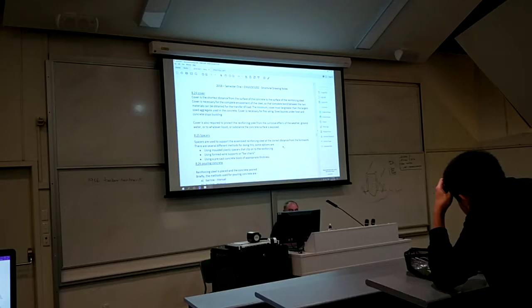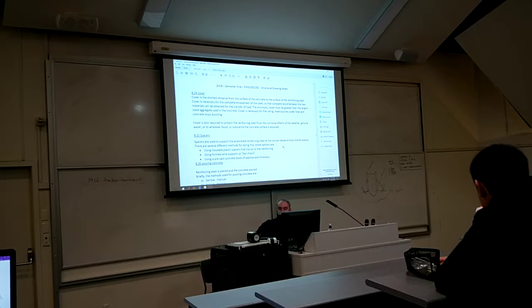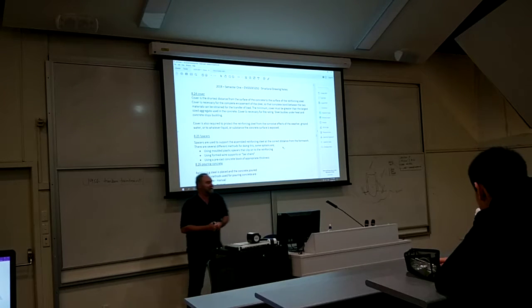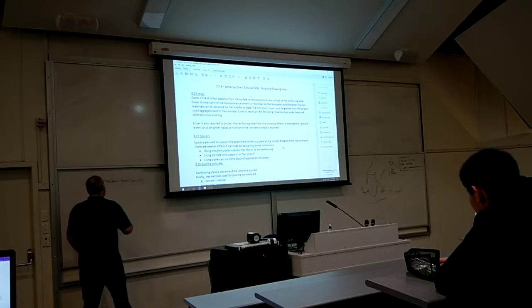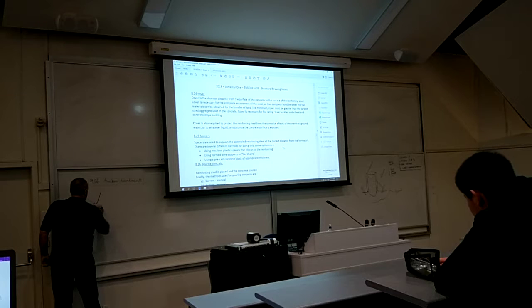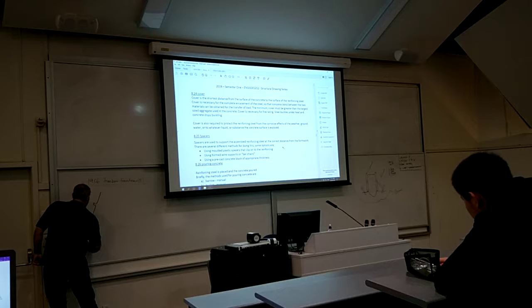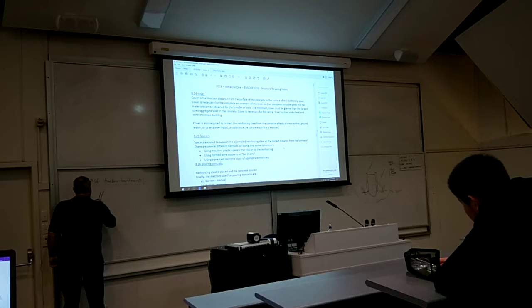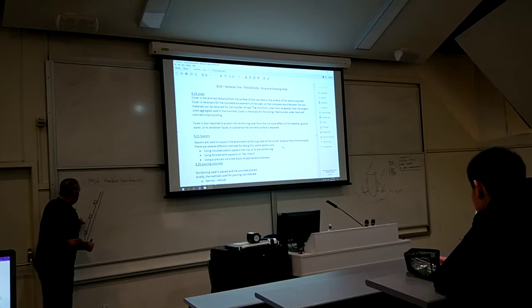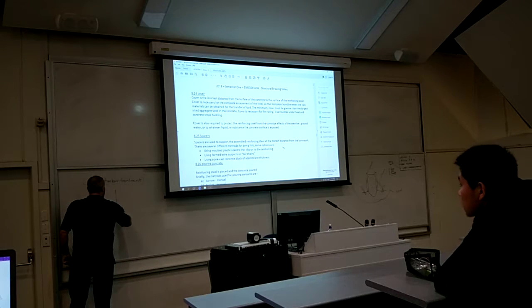So some of the methods that they use to set the cover is they have things called bar chairs, which are quite different to what I was used to when I was growing up. They are not the sort of bar chairs I used to go on. And they sort of look a bit like this, kind of weird. And the reinforcing bars will sit on these bar chairs that they make up, which is exactly the right distance apart, height-wise. I mean, they can also be sort of like that as well.